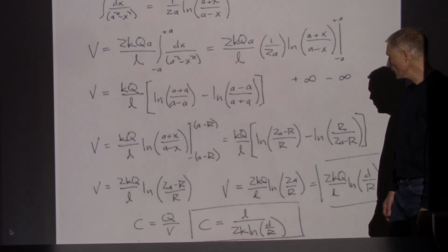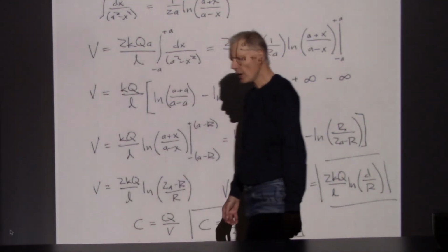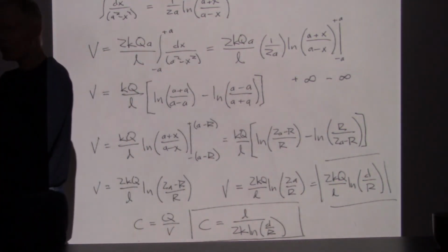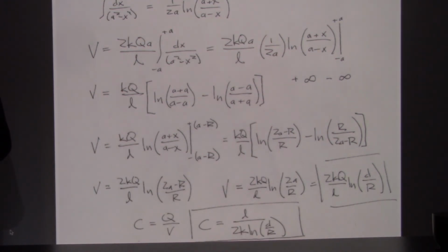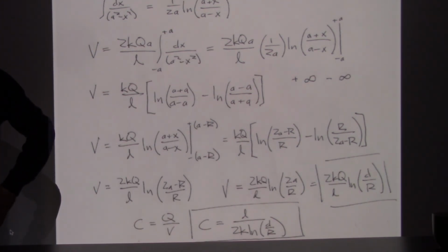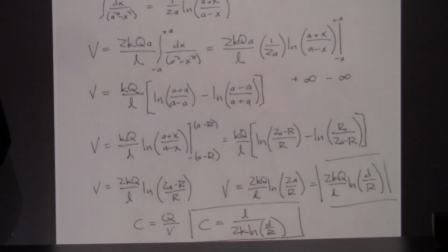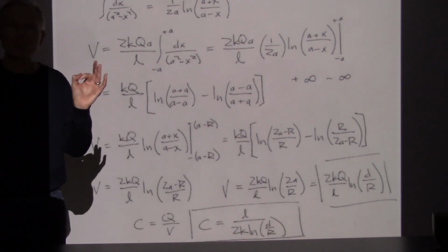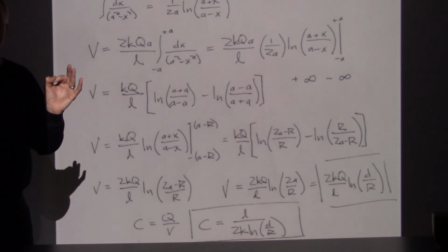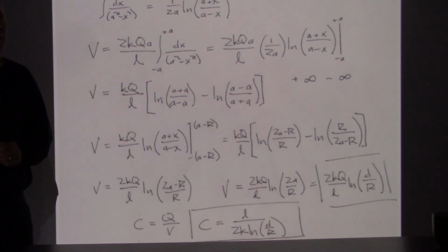And so we do have the possibility that if parallel wires become charged, if we end up storing charge on those, that there could be communication taking place between the two wires. We could have crosstalk. If I've got information transmitting along some of these wires, I want to make sure that the wires remain independent.